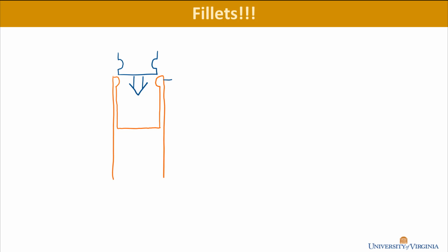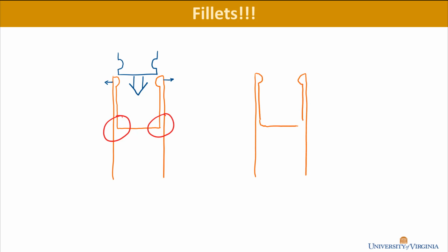This is drawn like 2 cantilevers where they each have a force on the end of it, where you see these 2 beams. This could be an annular snap fit that's round also, but the principle would be the same. And we know now that the places of maximum stress are down here at the base of these beams. And look what we have, 90-degree sharp corners. The fix for this is fairly straightforward. It's just to put in fillets, which will give you rounded corners and reduce the stress that's caused for a given deflection.